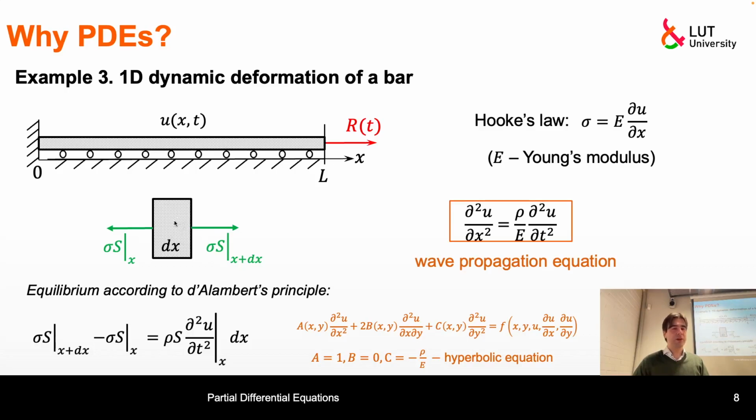Okay, and we require it to be in a dynamic equilibrium according to D'Alembert's principle, which means that if we add inertial forces into our equation, then it must work the same way as a static equation would work. So this is the balance of forces accounting for the inertial force on the right side. Or you can think of it as this form of Newton's second law. The idea is basically the same. Okay, and again, we need to use something for the constitutive equation.